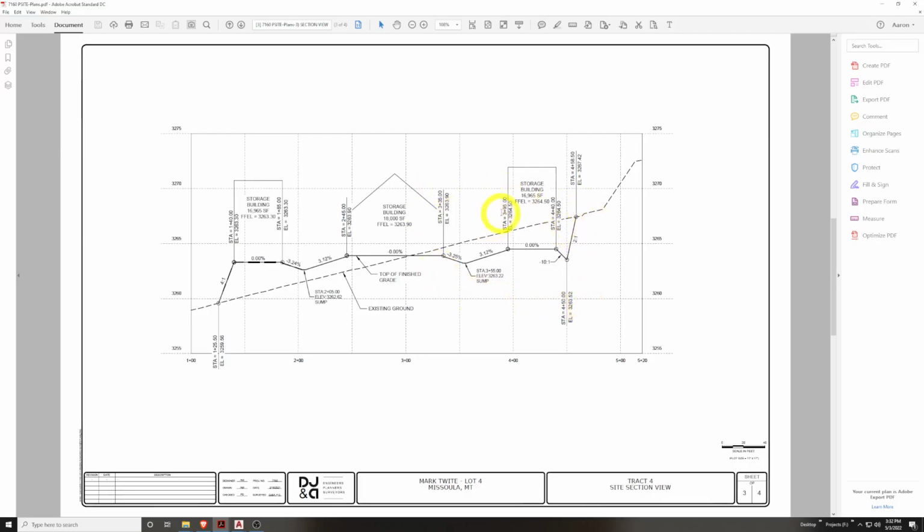Now, sometimes there's only so much you can do. You have certain constraints you cannot design around, or various things that get in your way, or bad soil in certain areas, or whatever. You need to haul a bunch of it out because it's junk. It's full of organic material or whatever. But depending on the site, you do your best sometimes to balance it so you don't have to have a whole bunch of construction and transportation costs hauling things in or hauling things off. So this is one huge analysis benefit of Civil 3D, and it gets used a lot, but the numbers are very critical to get right. They're very easy to get wrong, and they get very scrutinized when they're off.